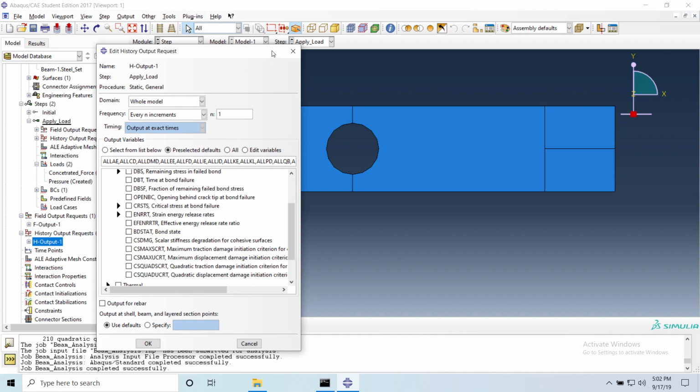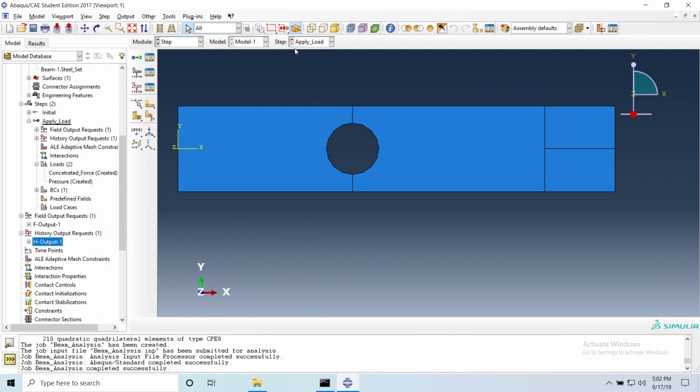So do we have element local orientation here? So if it's S11, we meant that it would be on the plane of 1 in direction of x. Correct. How do you know which direction plane of 1 is? The same as your base coordinates. It's global. So it's not local. What is local is your element numbering.